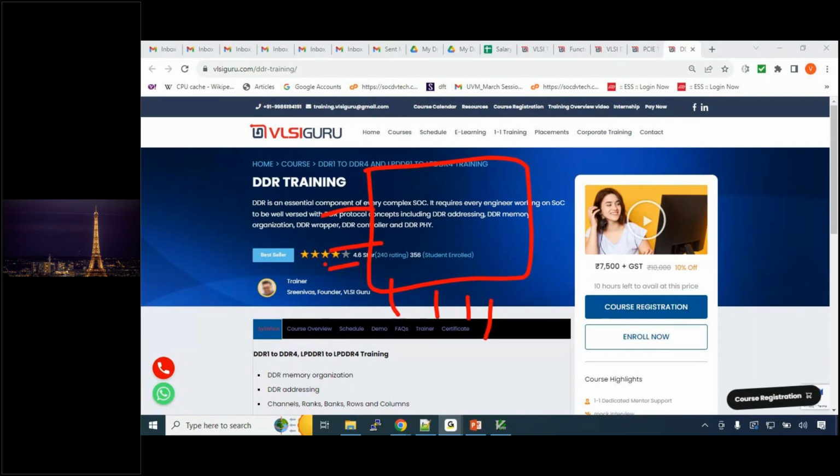MMC is a peripheral protocol because here you connect the MMC device. VGA is again a peripheral protocol. Every laptop has a VGA port, an HDMI port. These are all peripheral protocols. Then what are AMBA protocols? They are inside the chip, for the communication inside. Let's say a communication is happening inside the chip. That happens through AMBA protocols.